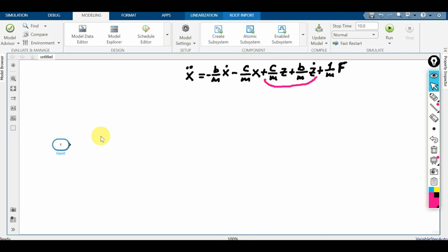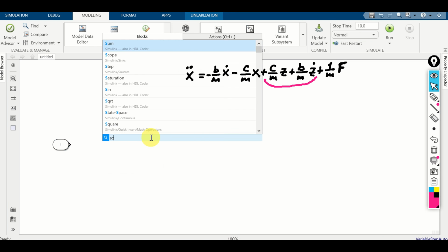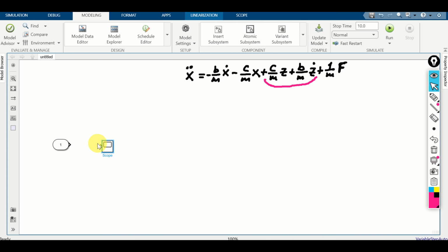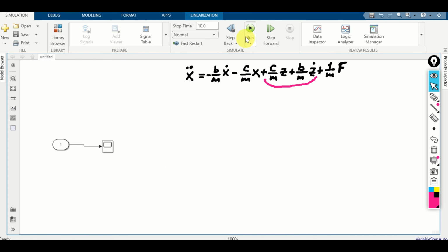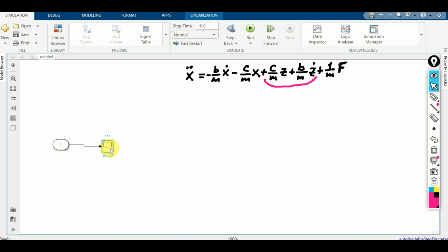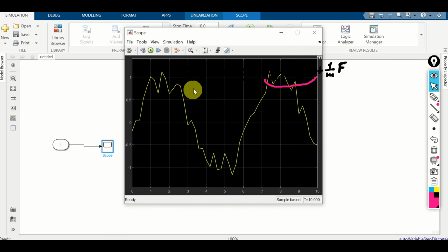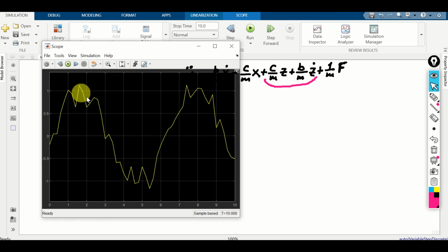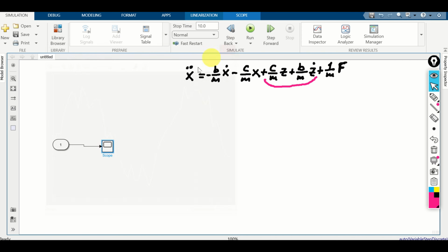This variable, or better to say, this array or structure, stores the time series of the disturbance, and click OK. Now, let's double check that Simulink can actually access this time series. The best strategy is to try to plot it. Double click here and search for scope and connect this block with this block. Now click on simulation and click on run. And double click over here. Here it is. We can clearly see the input disturbance. Good. Close this, erase the scope, and let's continue.